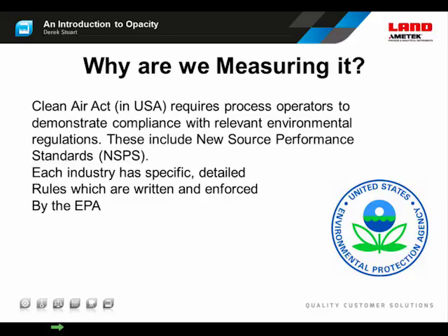So why are we measuring opacity? Well, in most countries there are regulations which govern the amount of smoke that's allowed to be emitted from a stack. In the US, the Clean Air Act requires process operators to demonstrate compliance with the relevant rules, and these are generally called New Source Performance Standards, which are performance standards that have to be met by any new source of pollution.